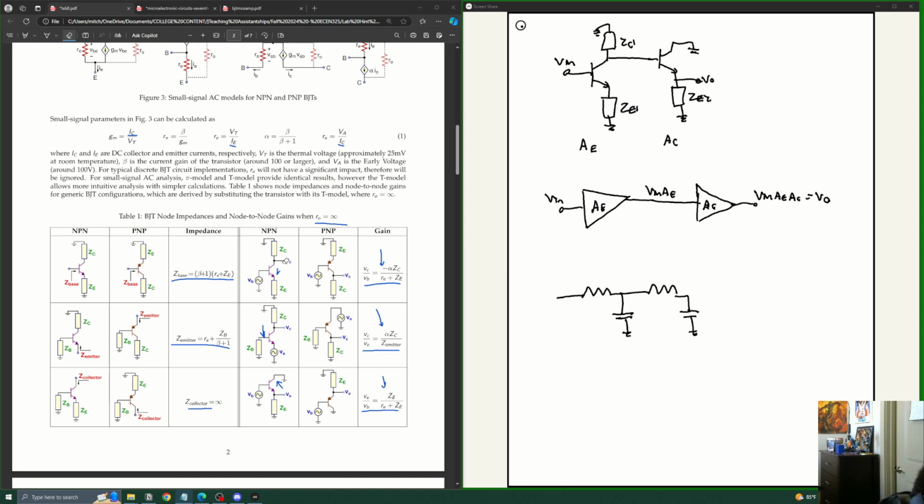And remember, the problem was that we were thinking, oh, well, we have two first order filters, so the transfer function is just these two multiplied to give us a second order filter. But the problem was that the first stage was not acting the same anymore, because by adding the second stage, some of the signal went forward to the second stage, which affected the properties of the first stage, right? And a very similar situation is happening here. The two BJT amplifier stages are not perfectly decoupled. By attaching the second stage, the first stage is influenced.